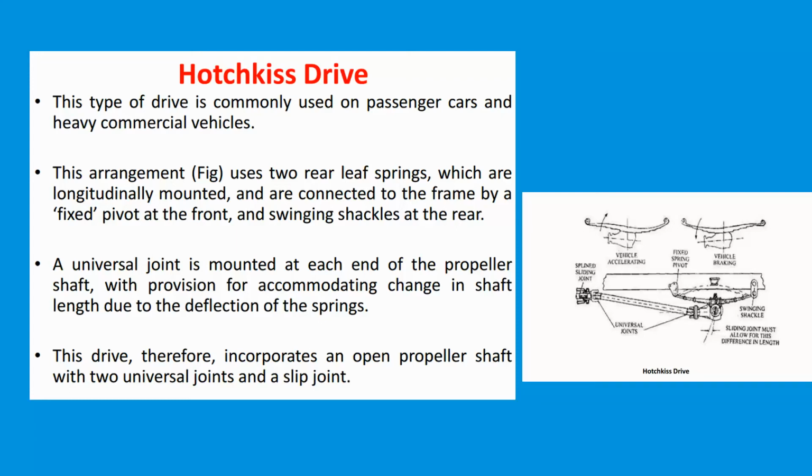In contrast, a torque tube arrangement uses only a single universal joint at the end of the transmission tail shaft, typically a constant velocity joint or CV joint. The axle housing is held fast by the torque tube, which anchors the differential housing to the transmission.